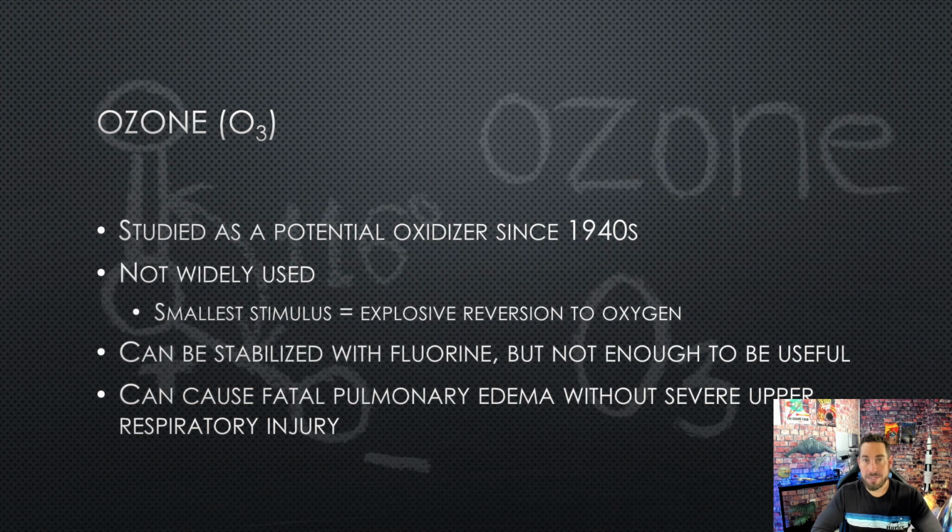What makes it attractive overall as an oxidizer is that its liquid density is a lot higher than oxygen. Remember, you want to maximize density so you can shove as much into the tanks as you can. And also, when a mole of ozone decomposes to oxygen, it gives off around, I think, 34 kilocalories of heat, which is awesome because that boosts overall energy performance, because the hotter you get something, the more propulsive force you're going to have. So it's got those two things going, the density and the thermogenesis of it.